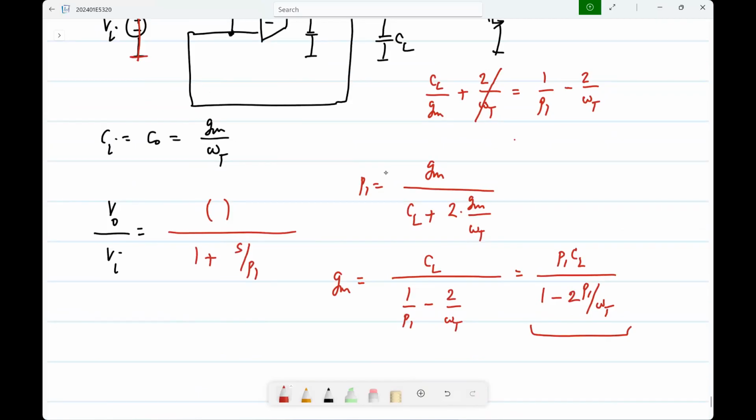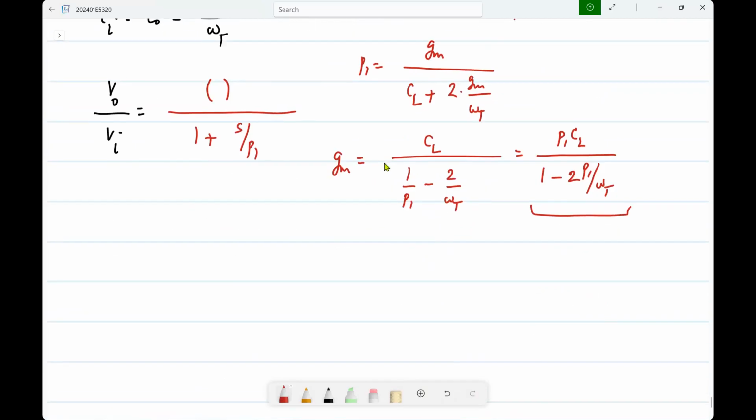So now this is a useful way to understand what happens to circuit design with technology, right? I had asked you to plot the bias current versus the pole frequency that you want to achieve. P1 is roughly like the bandwidth of this. Of course, you also have a zero, but P1 is the pole of the system. So that is like the bandwidth.